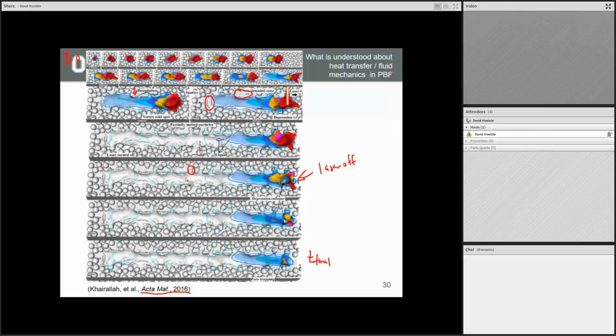But I think it's important to know too, when I went through that table of different suppliers of powder bed fusion systems, there's a company called Formlabs that's doing polymer powder bed fusion. They have a powder bed fusion system now too, and it costs around $10,000 or so. But with the polymers, you can do that in atmosphere. You don't have to do it in a vacuum or argon environment, so you don't have to have a really robust chamber, and that makes it a lot cheaper. Lasers, especially low power lasers for polymer melting, are pretty cheap. The higher power ones are expensive.